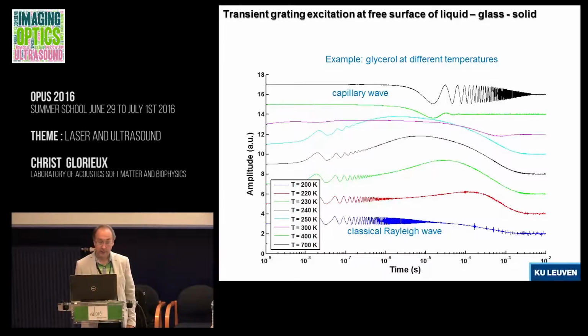Interesting is that if you look at glassy materials, because as I said we do material research, if you have glassy materials, everything becomes frequency dependent. Speed of sound becomes frequency dependent, becomes also complex. Even the heat capacity becomes frequency dependent, and even the thermal expansion, so the rate of expanding, becomes frequency or time scale dependent.